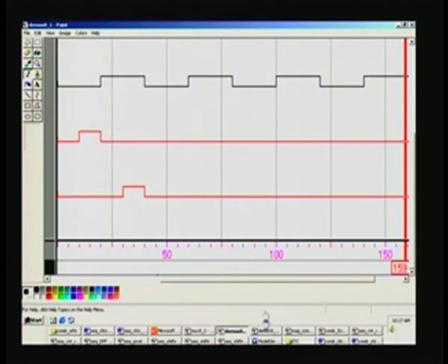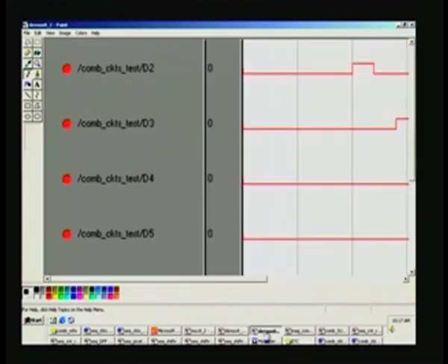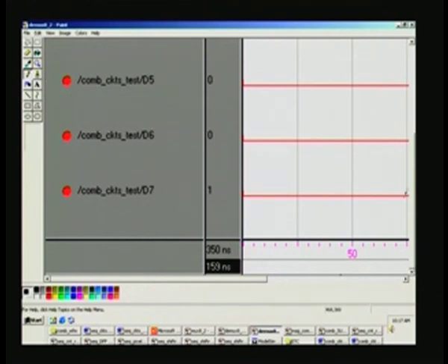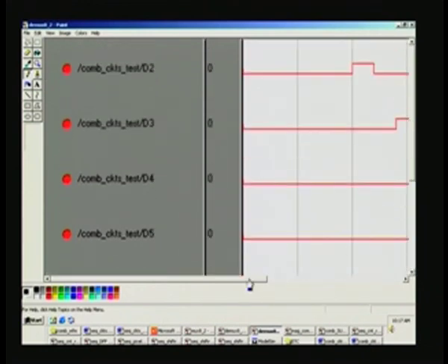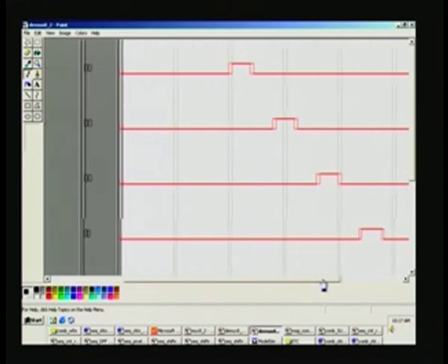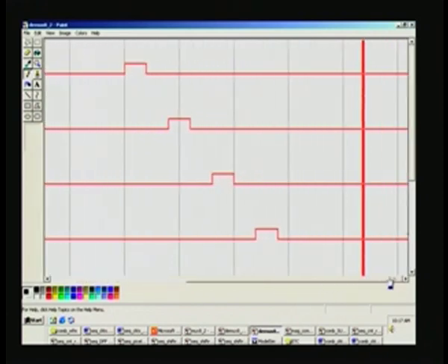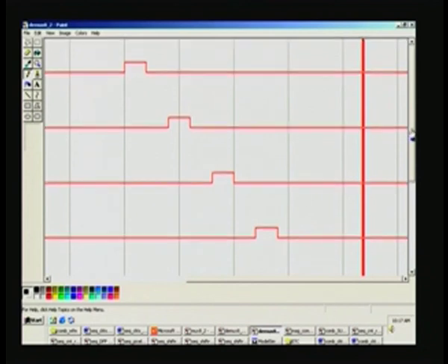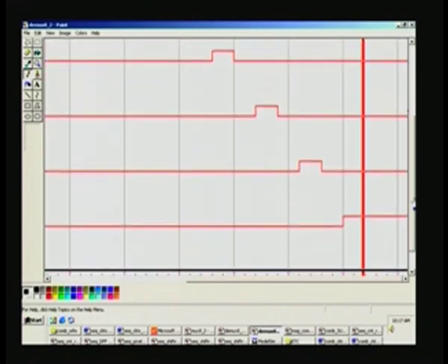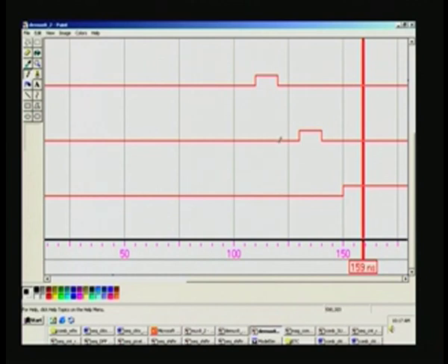And so then we move on to the other outputs as well, that is there in this waveform file. We had seen D0 and D1 there, and D first at this position and this position. Now in the third position you have D2 here, and you can see the time base is also the same, 50. So D2, D3, D4, D5, you can clearly see all of them going by one clock period as such. In fact, being combinational there is no clock period, it is every 20 nanoseconds that is happening.